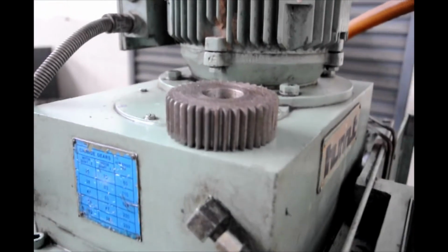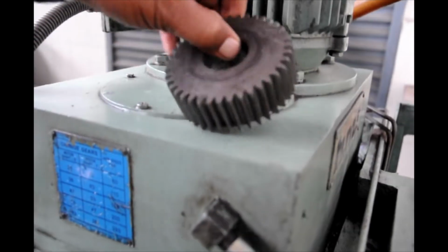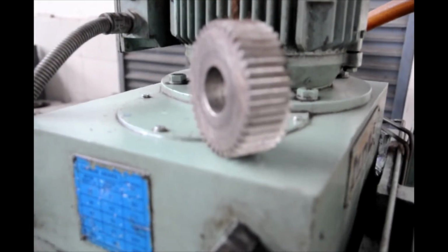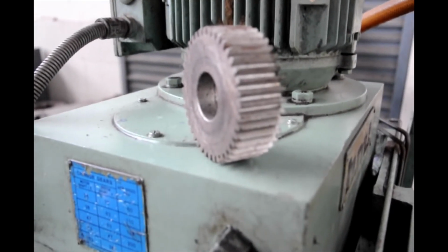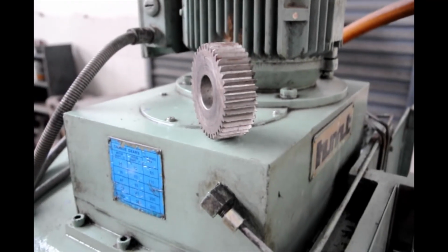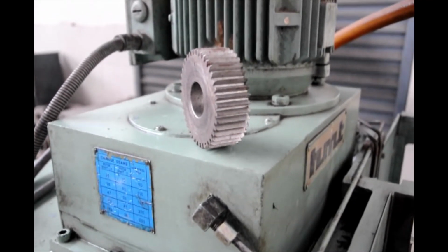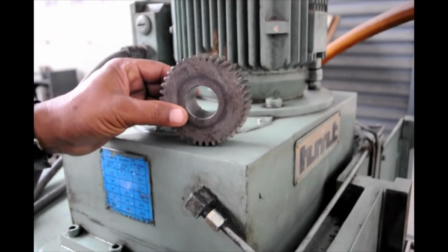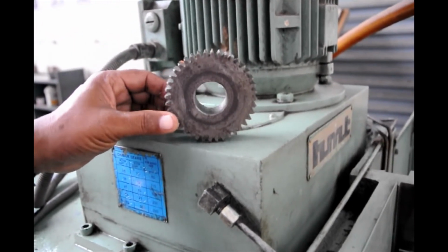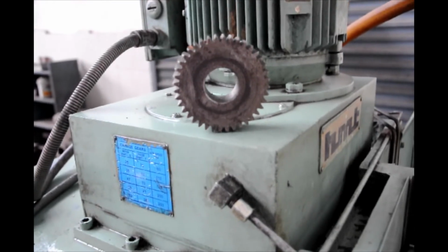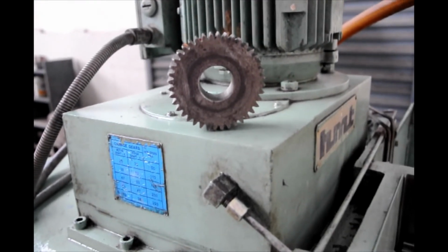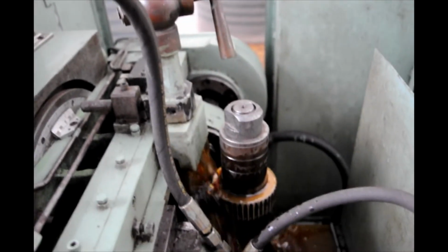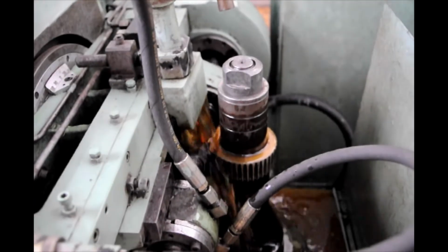There are different determinations which will be given, and the index motion. This index motion is fixed depending on the module. Once the module is changed, the index change gears and the gearbox itself have to be checked. So there are some settings for the different kinds of motions, different modules and different helix angles. Cutting is also possible for different helix angles with the hobs, and they are responsible for doing that.